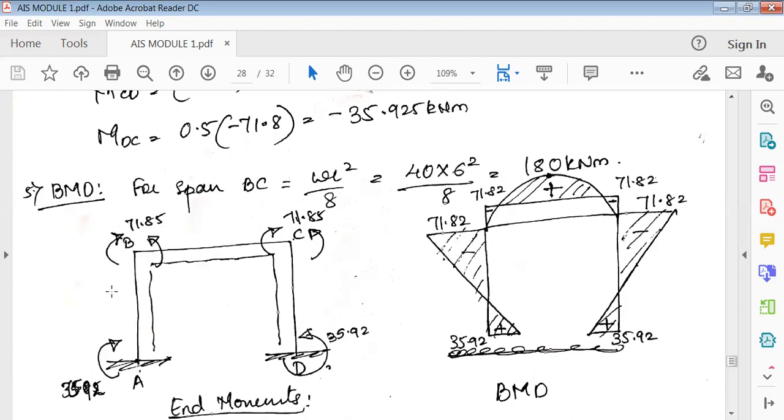Okay, drawing this diagram is very important. Based on this you can draw the bending moment diagram. All right, so now, as usual, we'll start drawing this. Now it is simple. You can see here, this is a positive bending moment. The arrow is trying to push this frame inside. We have to analyze the frame like this. So this arrow is trying to push the frame inside.